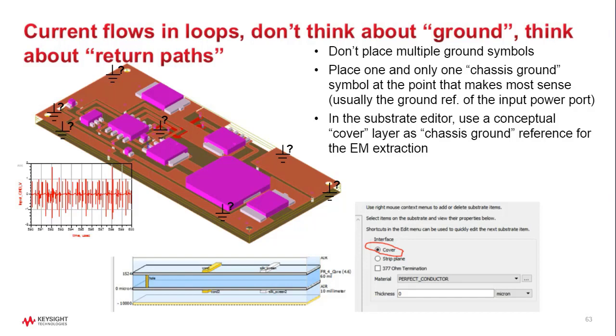So what we do here instead is we supply a pre-configured scenario where, when you do this EM extraction in the layout, in the PE cockpit, you get this reference of an earth ground, which is separate from having a 0 volt potential ground on the layout. So when you probe the layout, you'll find out that the potential on all the different metal points is legitimate.